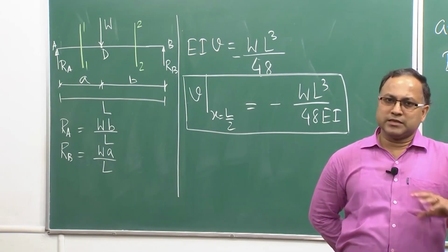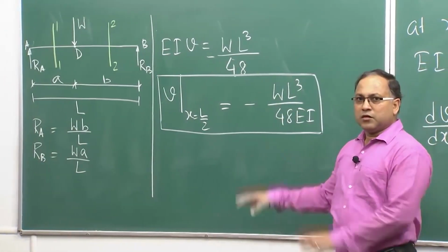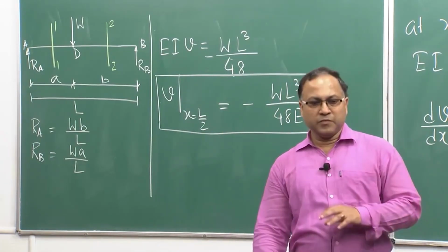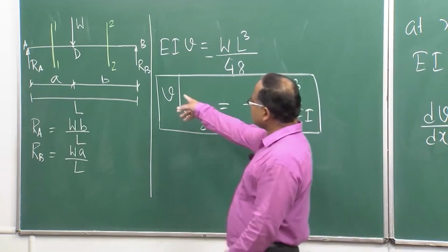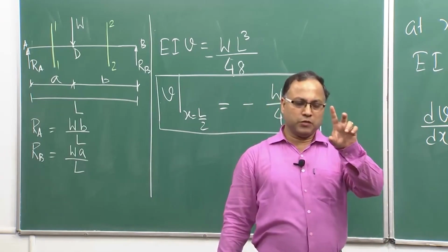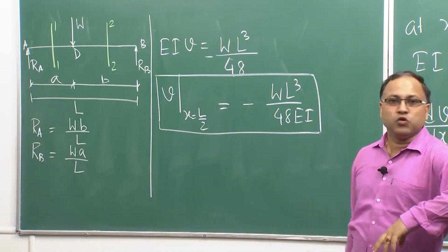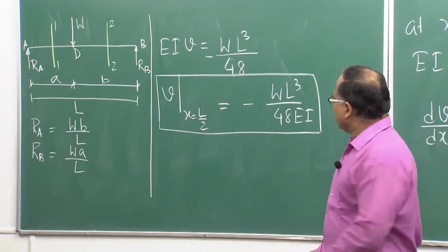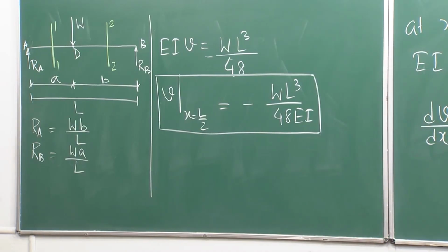That will be discussed later on, but at this moment we are trying to find out the deflection from our moment curvature relation. Because for getting your V, you are performing integration twice, that is why sometimes in some books it is also known as double integration method. So, this is the problem based on your moment curvature relation.